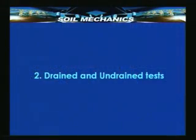In the case of shear tests as well, when the shear force is applied to the soil, depending upon whether there is drainage or not, the applied stress will get transmitted first to the water and then to the soil grains. And therefore, it is very important to know what is the condition with respect to drainage in a typical shear strength test. Let us see the next slide, drained and undrained test.